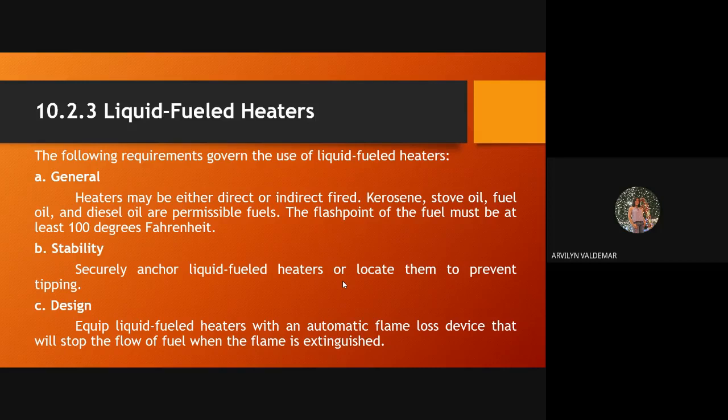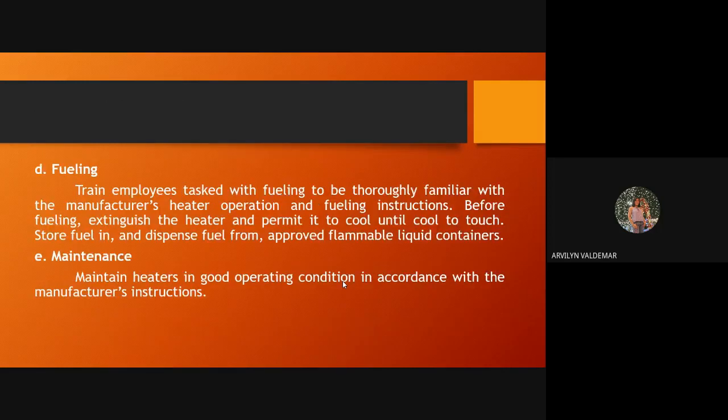For the design, equip liquid fuel heaters with an automatic flame loss device that will stop the flow of fuel when the flame is extinguished. For fueling, train employees tasked with fueling to be thoroughly familiar with the manufacturer's heater operation and fueling instructions. Before fueling, extinguish the heater and permit it to cool until cool to touch.